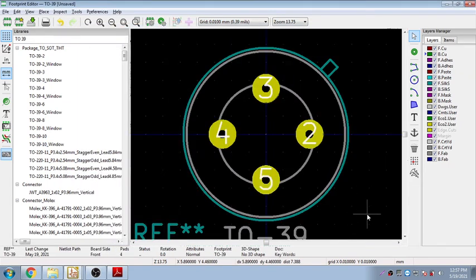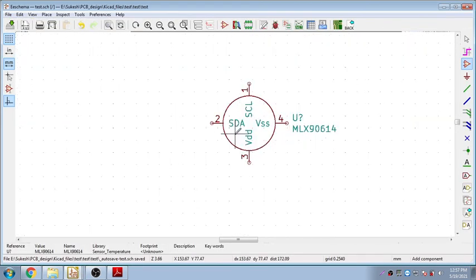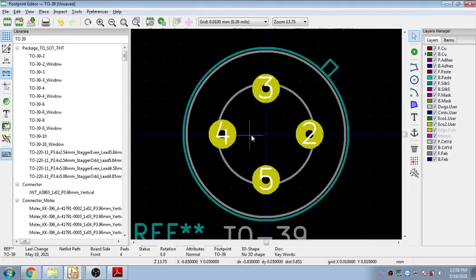Okay, now what we need to do is worry about the pin numbering. Whatever numbering is given is wrong, because if you look at the schematic here, we have started with the numbers 1 2 3 4. So our numbering in the KiCad library, the footprint, is also exactly 1 2 3 4. So let's see which is supposed to be 1, 2, 3 here, to match the actual device. Now this is nowhere having a physical dimension, it is just a pin name. So pin number 1 is SCL, pin number 2 is SDA. So we need to see how to map this actually.